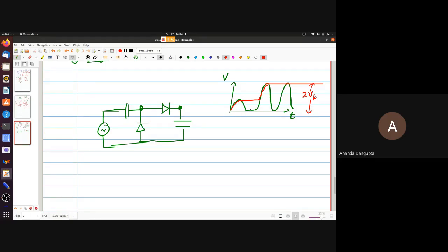The green line here is the output from the diode clamper, or positive clamper, and a peak detector always detects the peak. So if you just go by that logic, it should really follow the input until it reaches a peak, then it holds flat, then again it rises until it reaches this peak and then holds flat forever. Right? This is what you would expect. Is that correct?